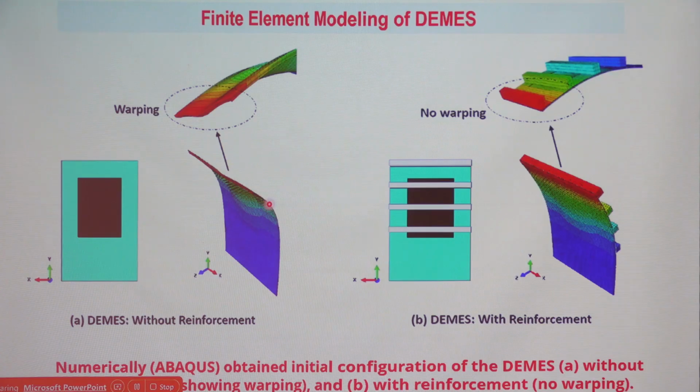So after developing a certain number of elements, you start seeing that your curve, for example, if it is increasing, the displacement versus number of elements, as you keep increasing the number of elements, either your displacement decreases or increases. It will follow one of the trends. So after a certain number of elements, whatever increase you give in the number of elements, your result for the displacement or stress, whatever you are measuring, will remain the same. So the curve will increase, then it will take a constant value.